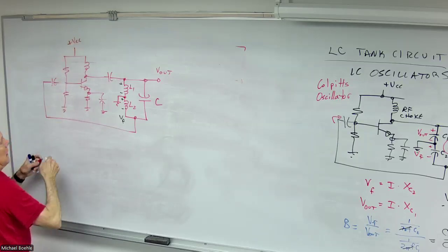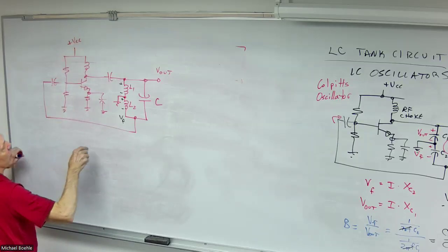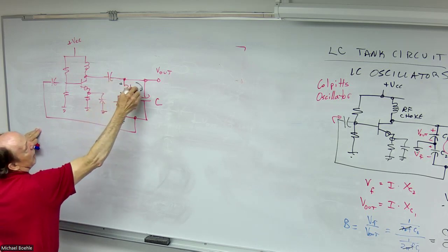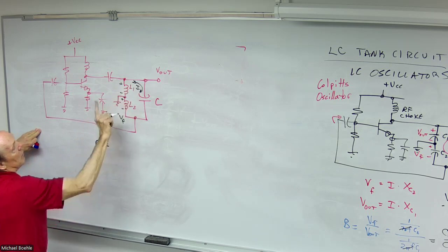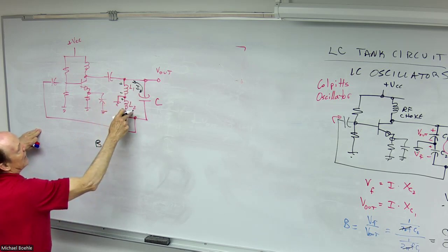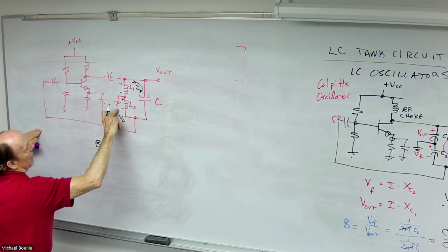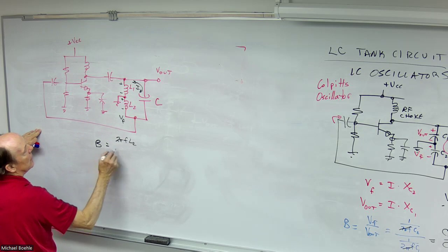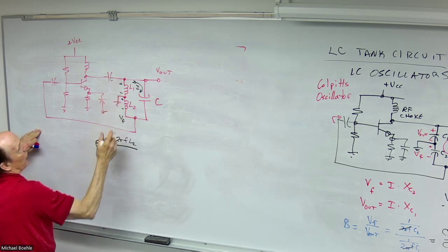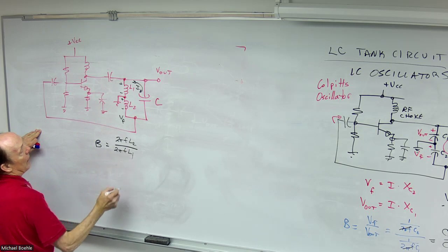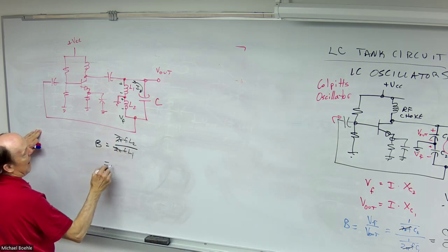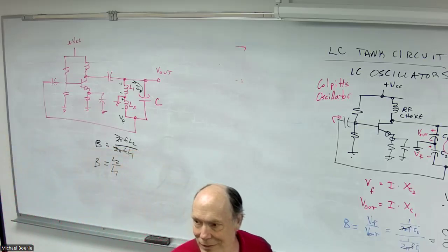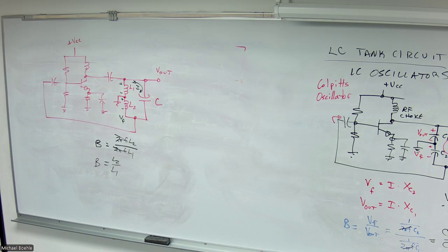Feedback fraction here, of course, is going to be what? Voltage is determined by the same circulating current, but the reactance that the feedback voltage is developed across is 2 pi f L2, and the reactance for the output voltage, 2 pi f L1. Feedback fraction is L2 over L1. A reverse, because of that formula for reactance.